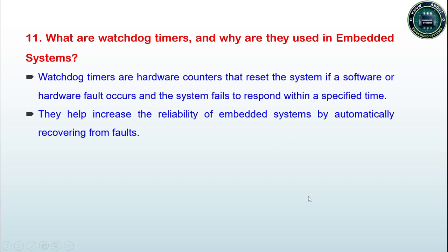Answer, you can see here. The watchdog timer is a hardware timer and it is a countdown timer, and this watchdog timer is used to protect your microcontroller whenever a software or hardware fault occurs in your embedded system. Whenever your software or hardware is not able to respond properly, the watchdog timer will start counting down, and when it reaches 0 or a minimum value, it is going to reset your microcontroller and it will protect your complete embedded system.